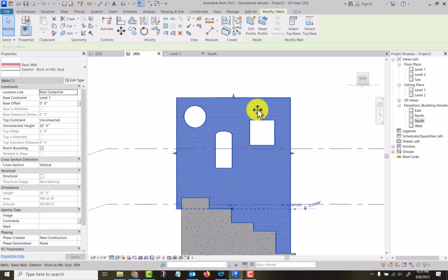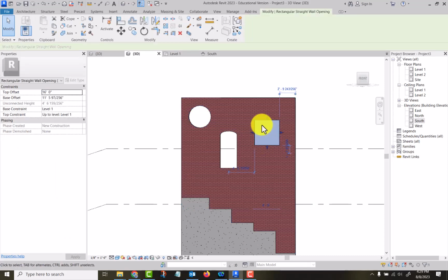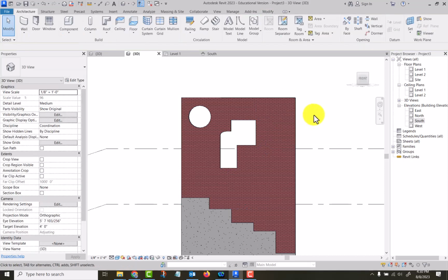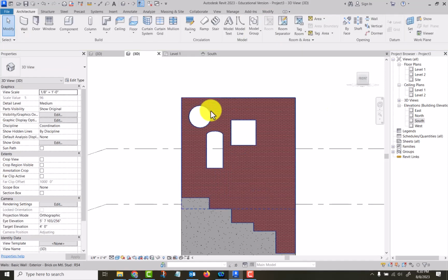These two, there we go. And so I can move it, and if I move it over into another one, they just morph together, okay? All right, but with this one, I cannot move it because it's part of the profile sketch. So you have to edit profile to get back to that.